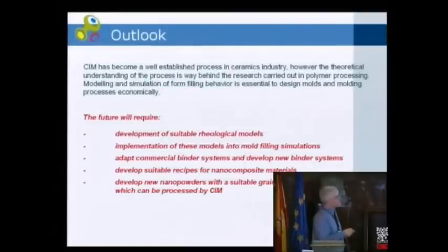If you put in, let's say, 10 or 20% of 100 nanometer or 80 nanometer powder into injection molding feedstock, your rheological behavior will not be killed. If you are introducing the same amount of a 10 nanometer powder, you can completely forget it. So these nanopowders have to be tailored with respect to the necessities of the molding process.